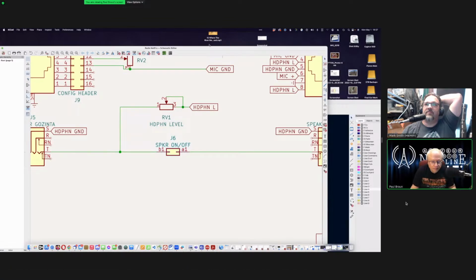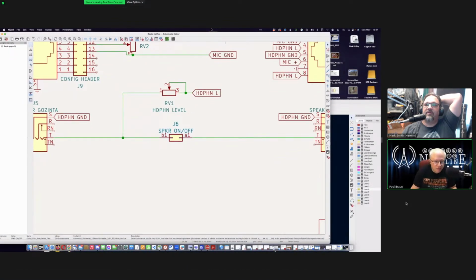There you go. I have pin header. I use the same pin header that we used on the user side one, which is why I was confused. The footprint is 2.54 millimeters, 2x1 vertical. And it says connect your 2x1 row letter first. There we go.